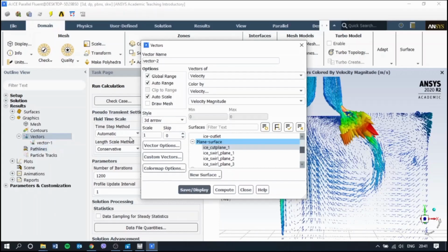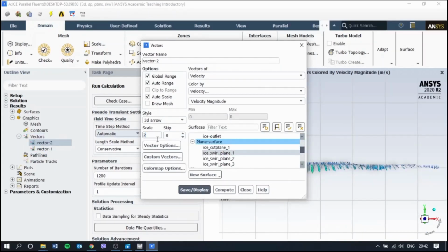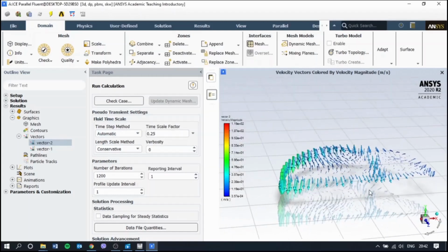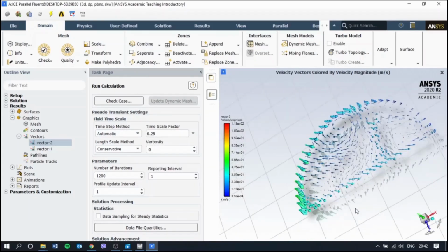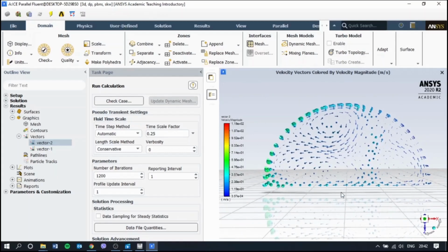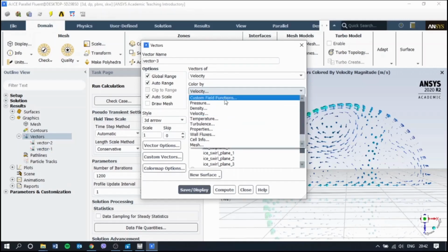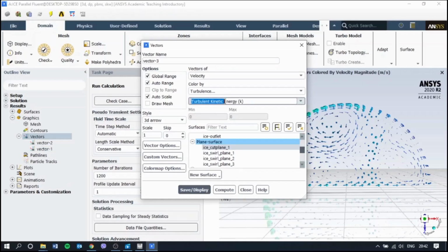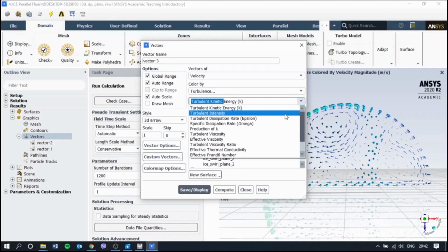In addition to this, altered analysis has been produced for the horizontal post-processing planes, displaying velocity magnitude and the significant swirl motions on the post-processing horizontal planes. Further analysis have been completed for turbulence. In this case, displayed is the turbulent intensity on the cut plane.